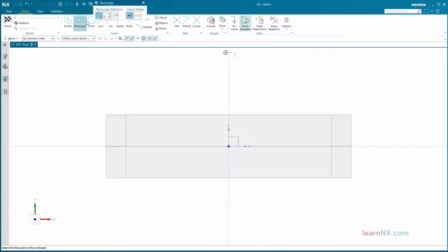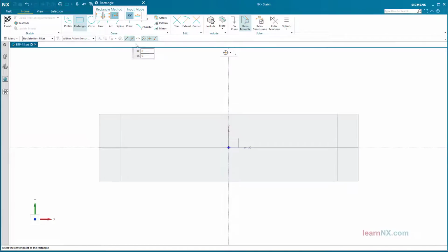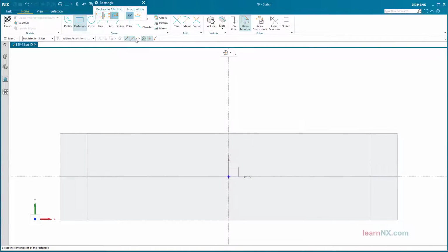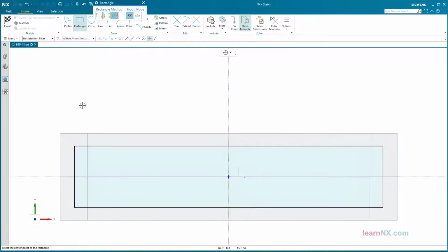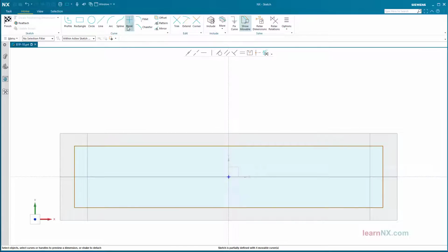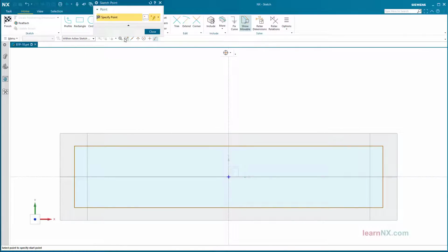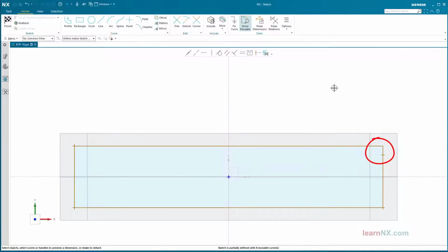You can define the positions of the screw holes in the sketch using a rectangle. Then set a point at each corner. But one of the screw holes is offset by 5 mm. This prevents the component from being mounted sideways.